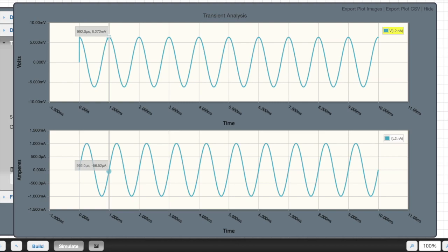So what that means is if I'm a particular electronic device and I need, let's say, 5 millivolts to run, at that time, I actually may not have sufficient current. So right here at this peak, the current is actually 0. And so if I need a full 1 milliamp to operate, I have to wait until the next peak, but then my voltage may be too low.